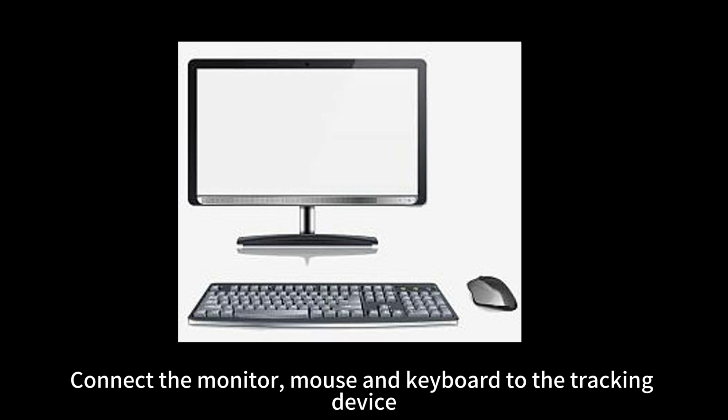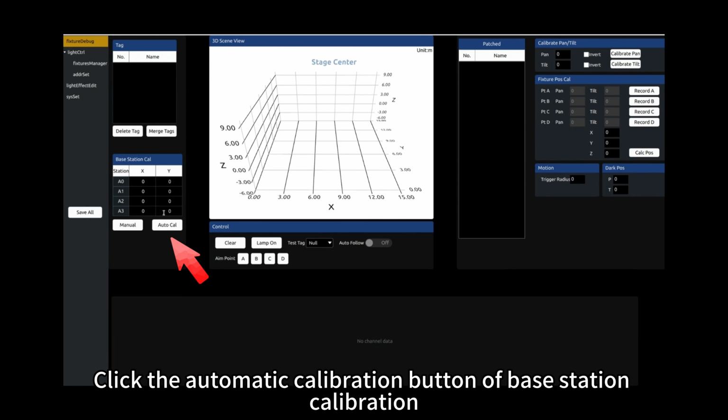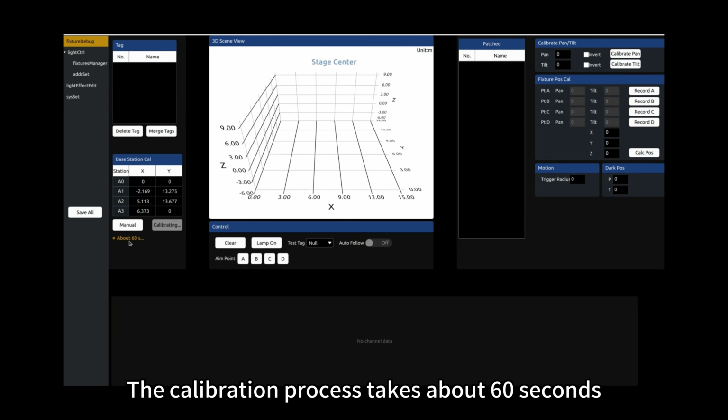Base station calibration and beacon merging. Connect the monitor, mouse, and keyboard to the tracking device. Start the tracking device. Enter the fixture debug page. Click the automatic calibration button of base station calibration. The calibration process takes about 60 seconds.